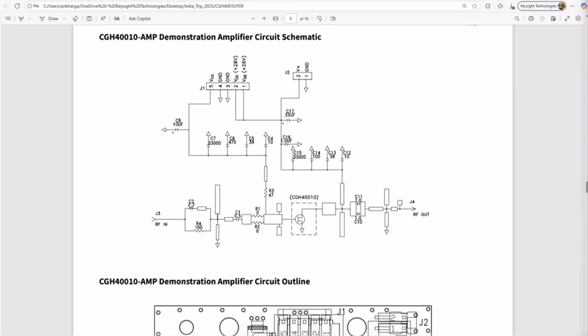Okay. And you will also find this kind of topology, and I have received multiple questions about why people like to do something like this. Why is this RC there? The simple answer is that if you're designing a broadband amplifier, this kind of topology, when you put this RC network, gives you more stability and a flatter response over a wider bandwidth. Also, something very common in power cases, even if you had a 0.5 picofarad capacitor, you will still put two components in parallel.